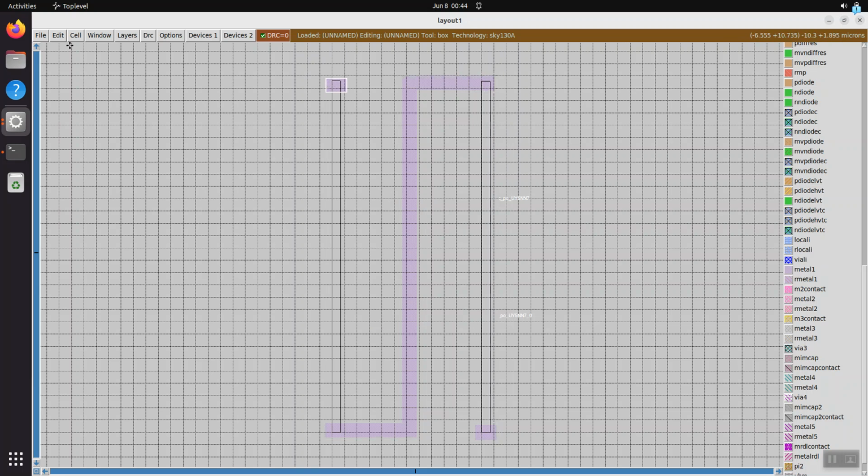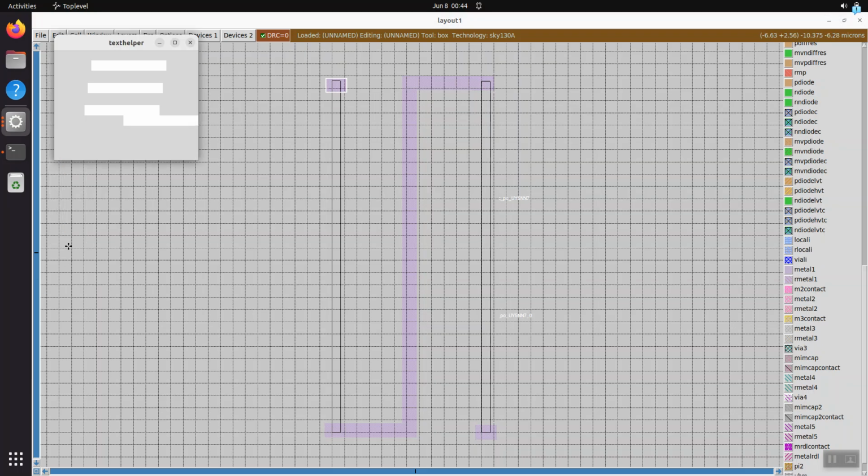So I select it, and there's a nice tool here in this kit where I add text and the text string. You've got to make sure you have the right name. Leave everything else the same, attached to layer default, but then you're going to make a port. Now, 1 micron is actually too high, you'll see. But if I put 0.5 micron, the letters should fit inside. Okay, they don't, but it's good enough.